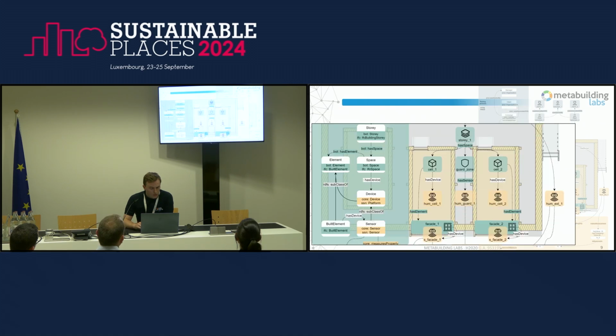And then you will see that I have added there element, and element could be BOT element, and it could also be the IFC built element. Because we wanted a way to represent the sensors and the built elements. We wanted to have them as a geometry, so the sensor is a geometry in IFC and then BOT is an element, because I believe there is no sensor in BOT. Is that correct? So for me, in order to be able to click it and to use it as a sensor and as a little box in the BIM model, I had to make this sort of artifice, because I need to distinguish between them.